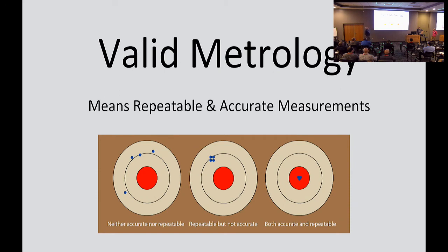Everybody in metrology has seen this for a while, but we're concerned with both accuracy and repeatability. And one of the things that Adam has found is that sometimes we will find CT results to be as repeatable as we could possibly hope for, but with an issue with accuracy. We'll say, okay, I've got really nice CT results. They are all lumped together. Now I do my CMM results, and they're even better lumped together. Uh-oh, wait a minute. There's a big shift. There's a bias in accuracy. That's something we put a lot of time into thinking about, to make sure that we have accurate and repeatable data.